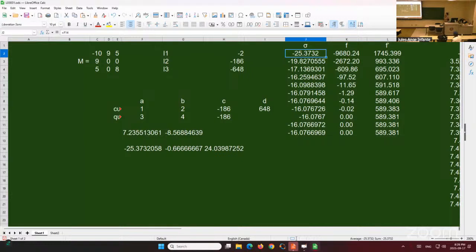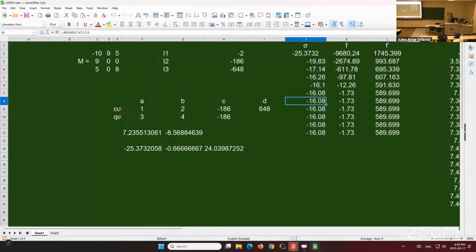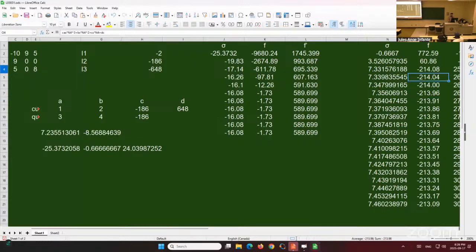This is one thing also. I noticed here that I kept a horrible amount of decimal places. You don't need to keep all these decimals. Do I need a fraction of a kPa? Let's say a hundredth of a kPa is all I need. So I round the result to 2 decimal places. Then you see that I converge faster. And I bet this one would benefit from the same treatment.